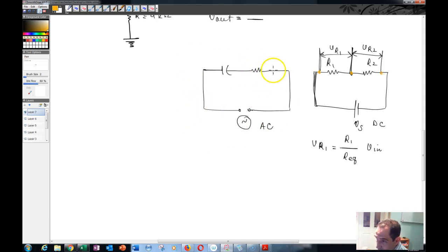You don't usually go and put your oscilloscope ground clip at any point that you wish in the circuit. It has to be the circuit ground. So for that basic reason, every voltage measurement in an AC circuit is referenced to ground. But anyway, I'm getting off topic.